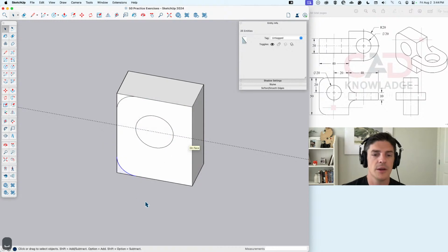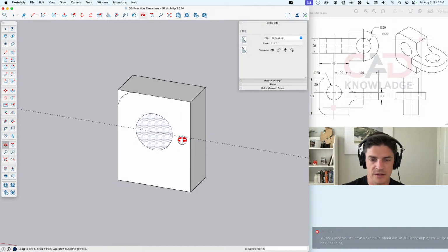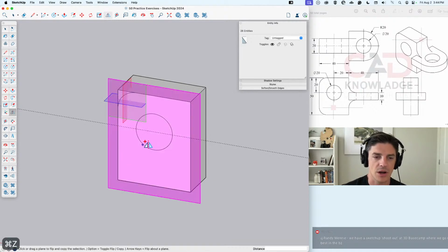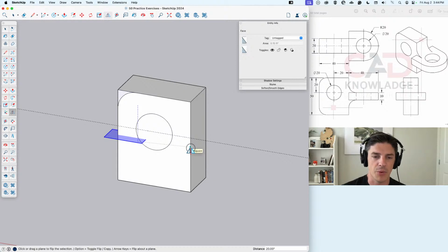That's a nice thing about using guides and not breaking geometry, because this circle is not centered on this. If I want to flip this equally to the bottom, I need to flip it referencing something that's halfway down. This guide is not, so if I flipped it, it's wrong. If that was an edge that I used, if I drew an edge to infer, this midpoint wouldn't be here because that edge would be cut and they would have two different midpoints.